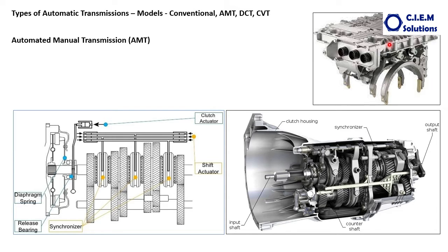This particular unit has inside it the hydraulic fluid, one TCM, some solenoids and a hydraulic pump, everything is there. So again the TCU takes the signals from the various components of the vehicle, processes them and sends the signals to the various solenoids to operate the clutch and to shift the gears as per the dynamic driving conditions. The main advantage is that the driver is free from clutch operation and gear selection. This transmission also has the provision that, if required, you can have a manual shifting mode as well.